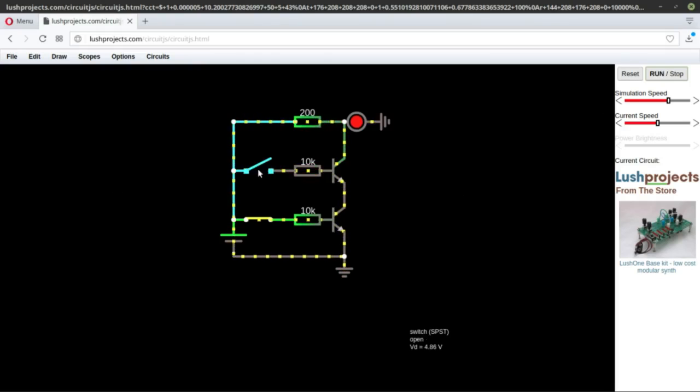When I turn this one off, then this transistor turns this line off, and when I turn this one off, then this transistor turns this lane off. When both of them are off, then obviously this is a NAND gate. So for a NOR gate, for an OR gate, I have to change the behavior.